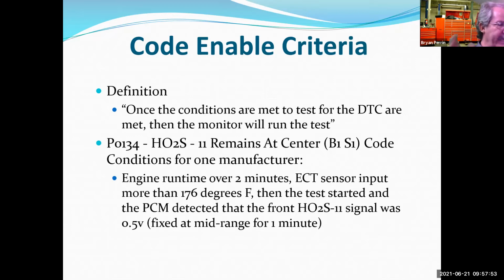And so when we look at our level 1 diagnostics, part of that is not only getting information from the vehicle, but also getting information about the code, right? Is doing research. What did the computer see that made it unhappy? Is there a pattern failure for this?